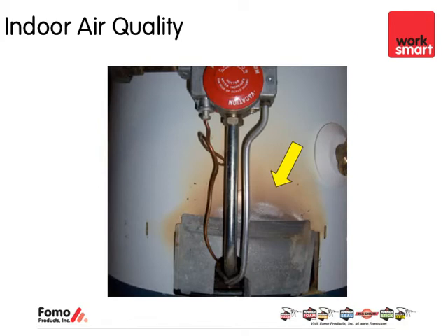The issue you have here is that the combustible flame is creating carbon monoxide, which creates a very dangerous indoor air quality problem. It should be addressed, again, by addressing the air sealing of the home, reducing or eliminating that stack effect. That could have a dramatic impact on the proper functioning, I guess, if you will, of this hot water tank.